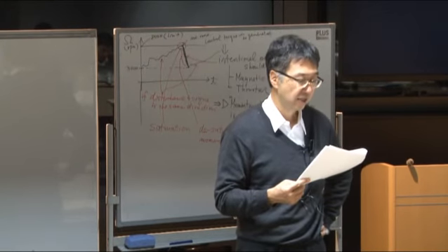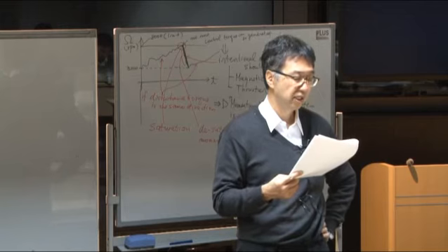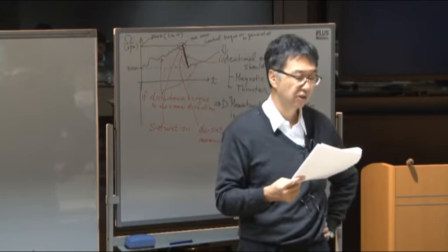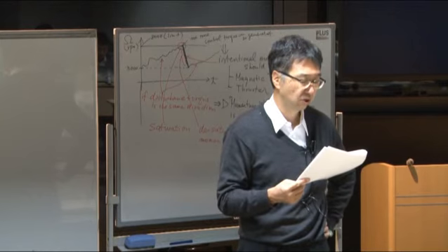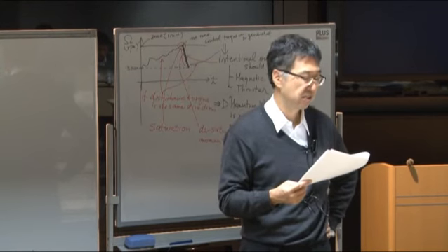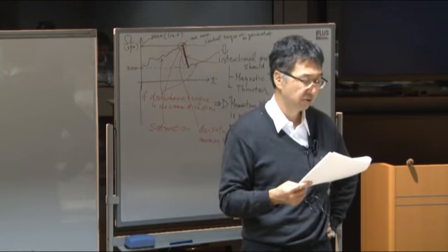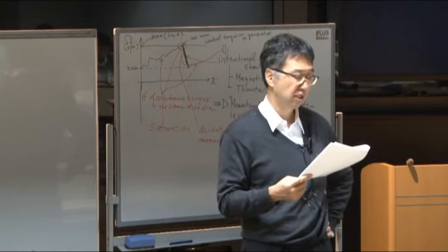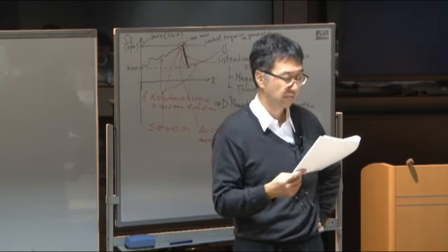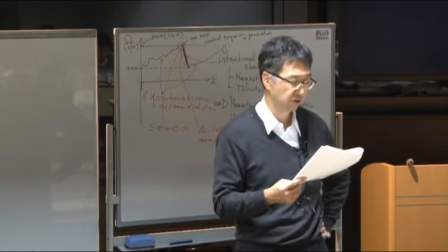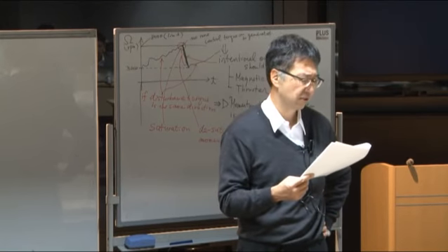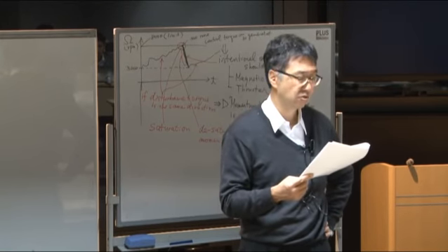And as I said, the solar radiation pressure torque and the aerodynamic torque will almost be the same at an altitude of 1,000 kilometers. Maybe the cross point between these two factors, aerodynamic and solar radiation pressure torque, occurs at around 800 or 1,000, in the log scale around 3.